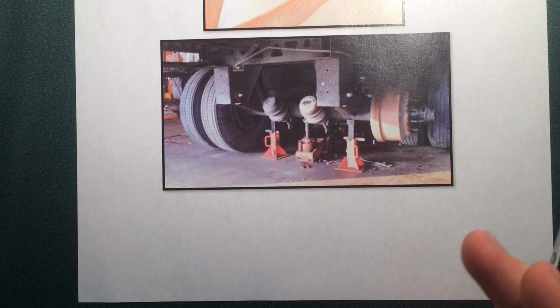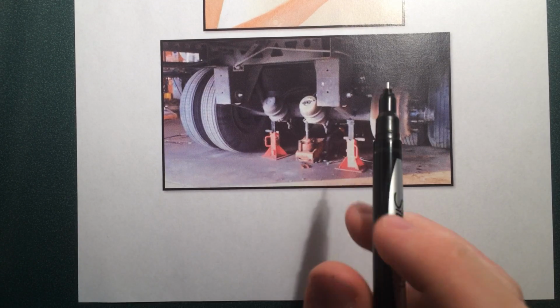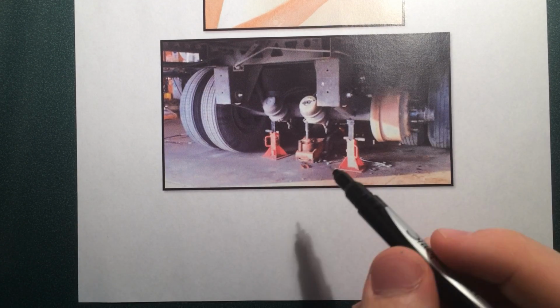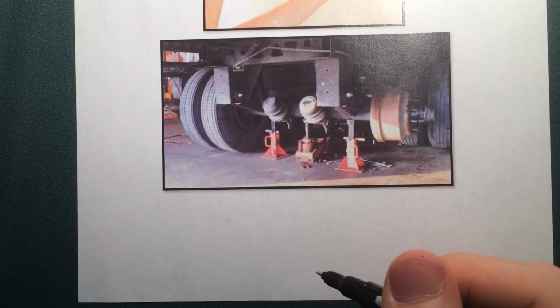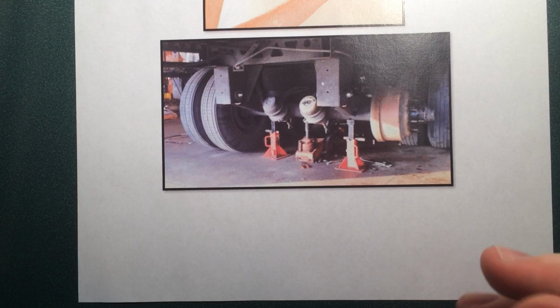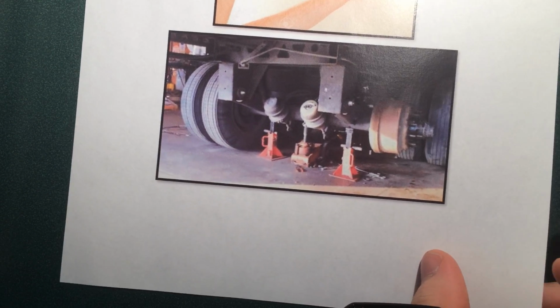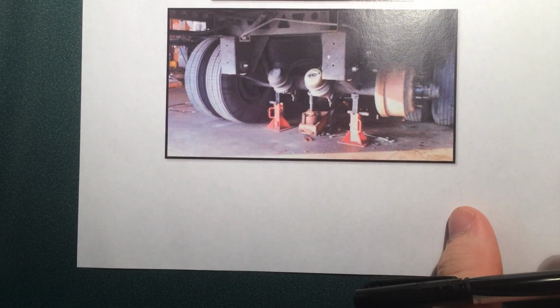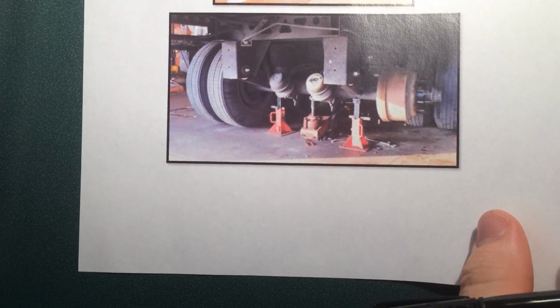So this is also a torsional bar, and we can analyze it using the power, right? If the truck has 400 horsepower, what should the diameter of the axle be so that when it takes off it doesn't just shear off. Alright, and of course there's lots more torsional bars, and I encourage you to think about torsional bars in your everyday life and think about how you can apply the principles you used in this course to those everyday examples.